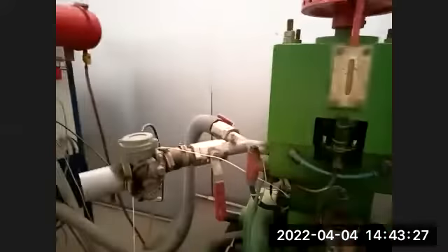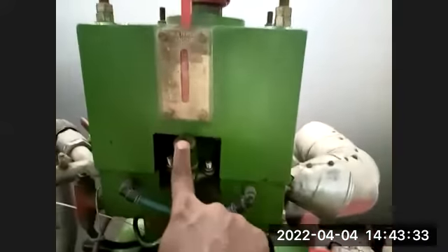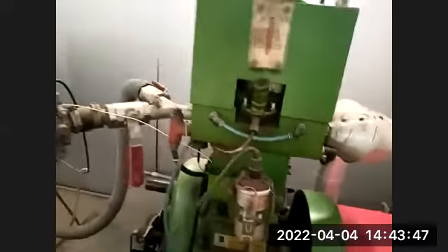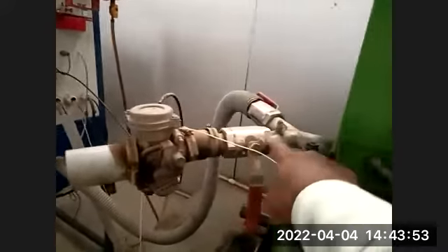And we have another system over here which we can connect to another tank, the petrol tank. So we can have this engine running on both fuels, and that is why we call this a multi-fuel engine. When it is running as a multi-fuel engine, we will replace this injector with a spark plug, and from this ignition system we will give high voltage electric supply to the spark plug, and we will give the fuel mixture inlet to this carburetor. It will be supplied to the engine.